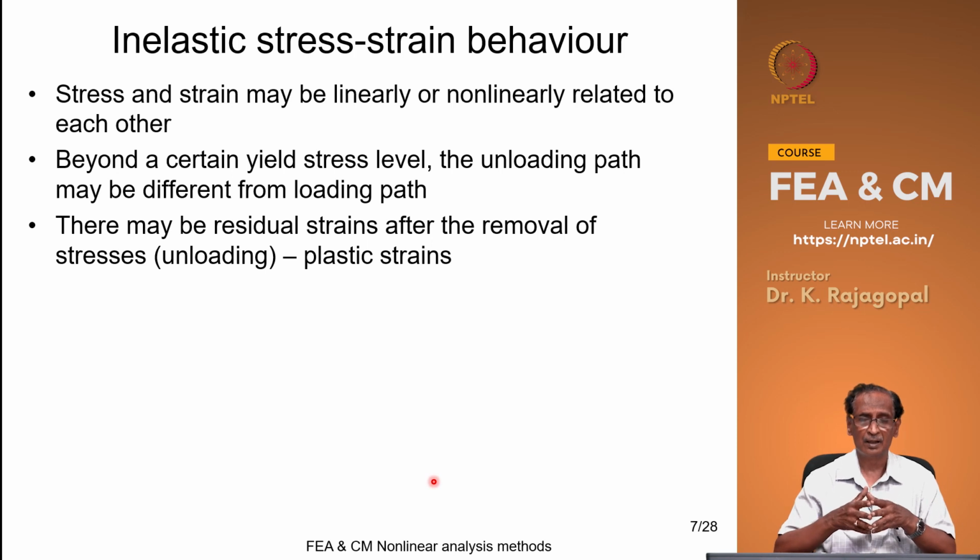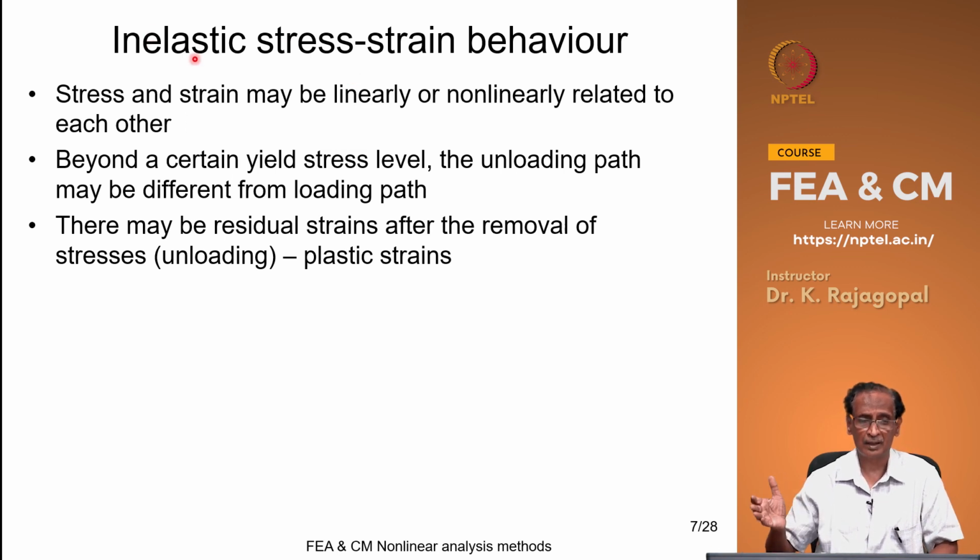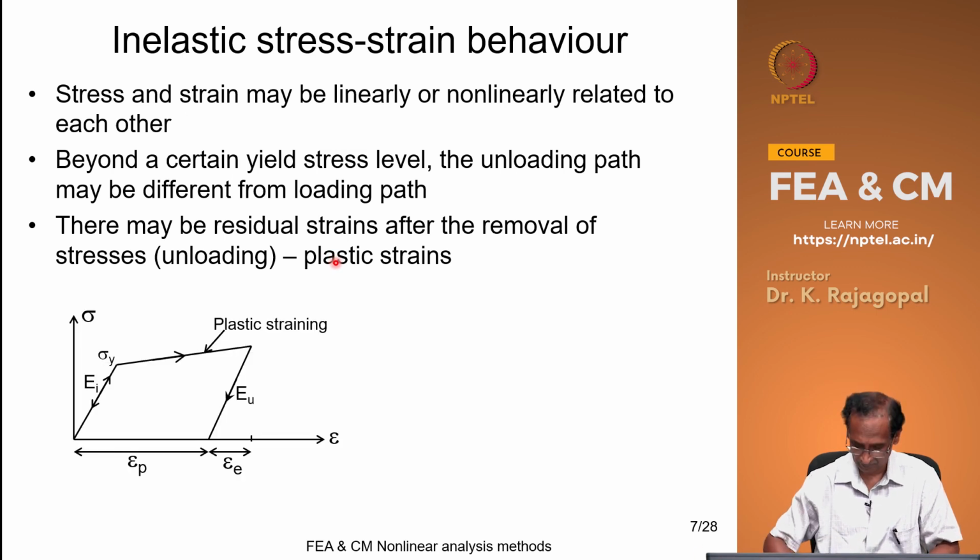Similar to your linear and nonlinear responses, we could also have inelastic stress strain behavior. Inelastic, that is not elastic, and the stress and strain may be linearly or nonlinearly related to each other, and beyond a certain stress level, the unloading path may be different from the loading path, and there may be some residual strains after the removal of stresses, that is unloading, and we call these permanent strains as the plastic strains.